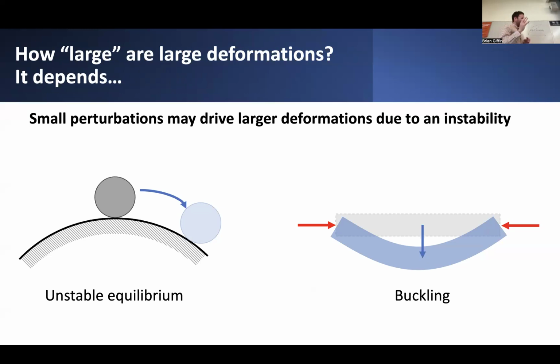And partly the issue has to do with that P delta effect, especially when you're considering things like buckling analyses. Even just a small amount of transverse deflection of this beam, or maybe this axial column subjected to purely axial loading, even just a small amount of transverse deflection under high axial loading can drive an instability.